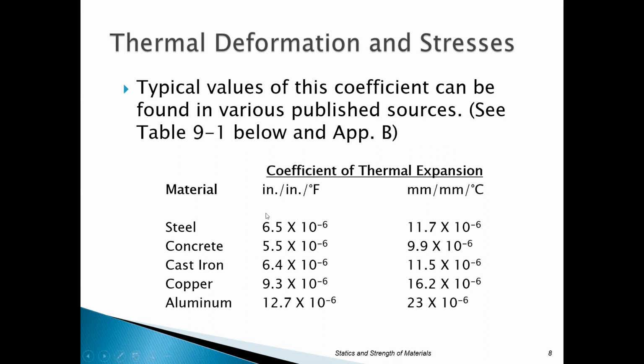And notice the unit, it's inch per inch per degree Fahrenheit. So basically it's just per degree Fahrenheit. This just kind of cancels out essentially. Now, it's important to understand it doesn't really matter whether you're inch per inch or foot per foot. It'd be the same number, but it is important that you use the right temperature type, either Fahrenheit or centigrade. Notice they're quite a bit different, so you've got to make sure that you're using the right one.